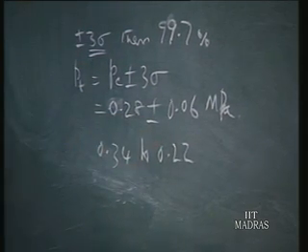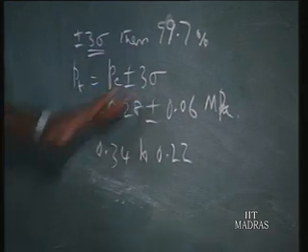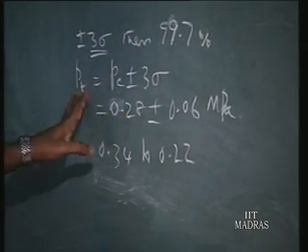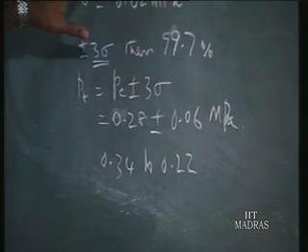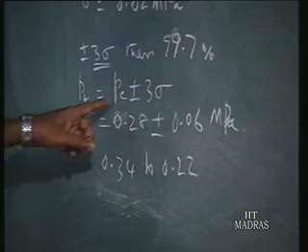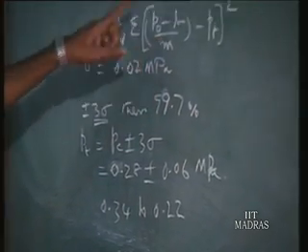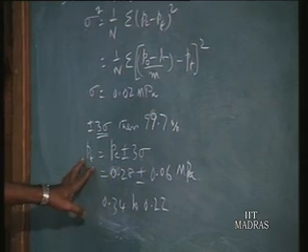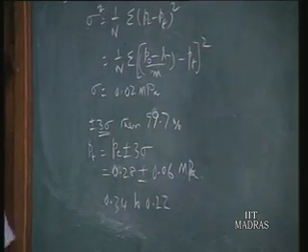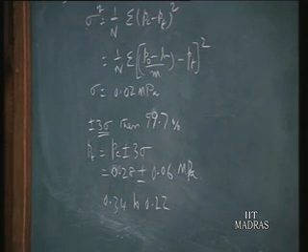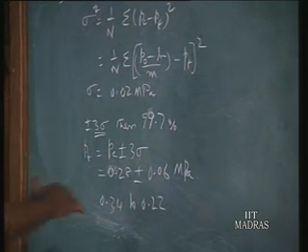So we arrive at the error of the instrument. That is, after recalibrating the pressure gauge, we can specify the new accuracy of the instrument like this. The corrected value should be found by using this equation. That corrected value with the 3 sigma limit then gives the true value. The true value, as always, has a range within the 3 sigma limit. So that is our recalibration: for a given reading, what should be the correct reading and its uncertainty. That is what we have found now.